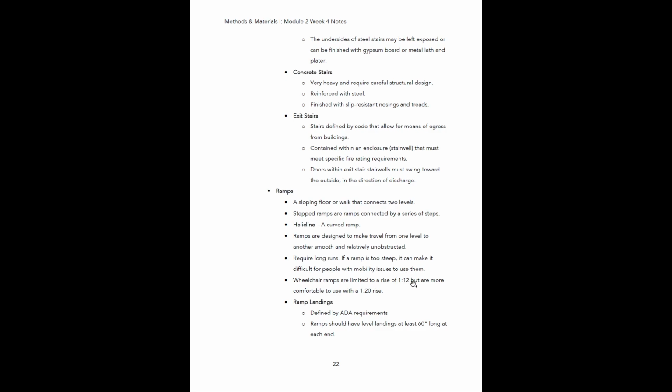As you can see, if you're only going upward 1 foot for every 12 feet that you walk, these ramps are going to have to be really long. If the door is 3 feet above the ground level, that's going to be 36 feet in total length of the ramp. So they're really long and they take up a lot of space, but that's what you need.